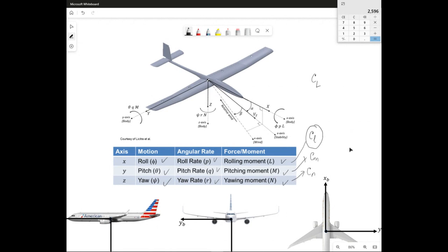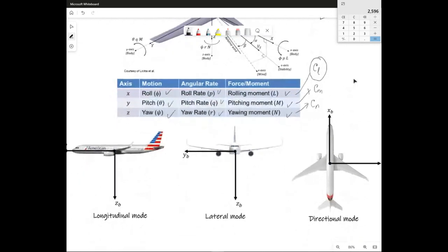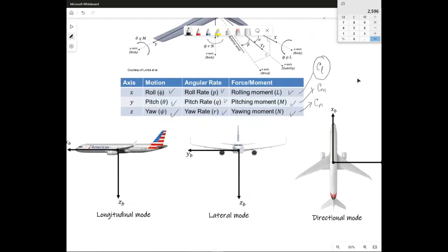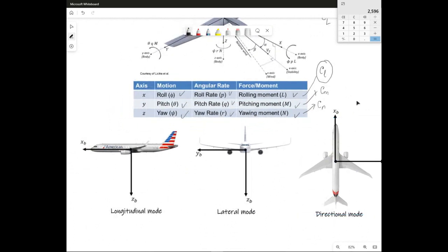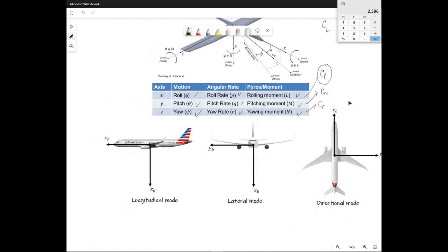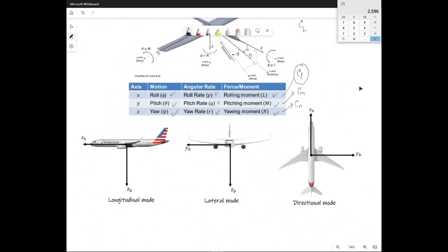But when you talk about stability, you could also simplify that in terms of analysis. People always make simplifications about how you look at the motions of your aircraft. Now, you could divide it into those six degrees of freedom, right? The aircraft is moving in six degrees of freedom, and those six degrees of freedom you could divide into three kinds of modes.